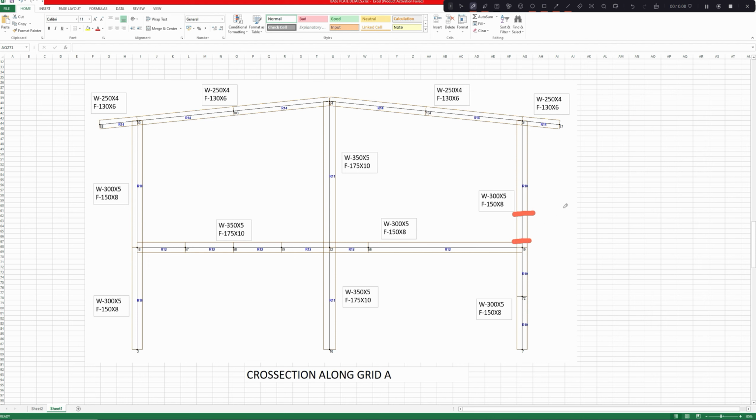But it depends on what the transfer limit is. The design of this column splice will be similar to the end plate moment connection having axial compressive force. So let us first draw the various connections and name them.